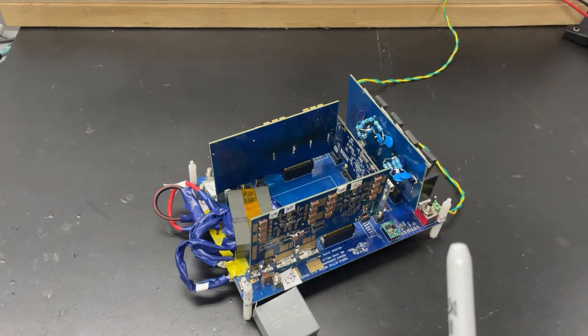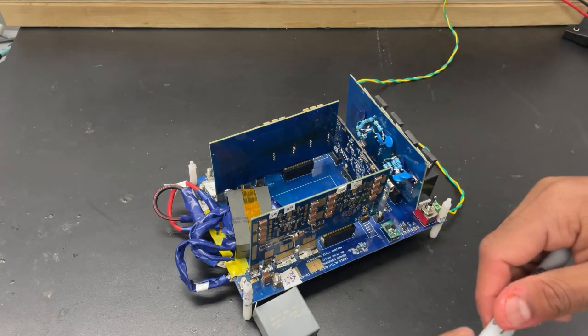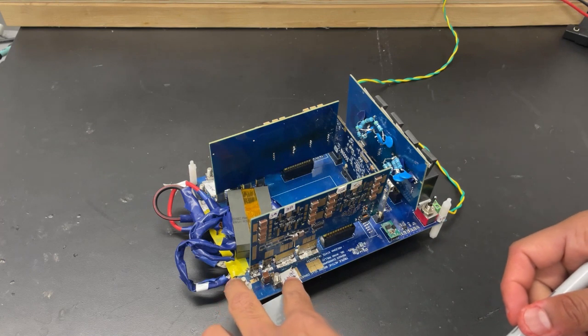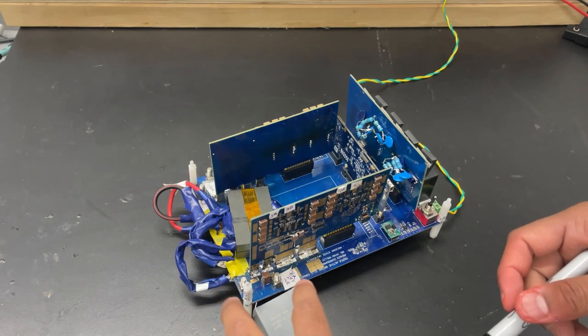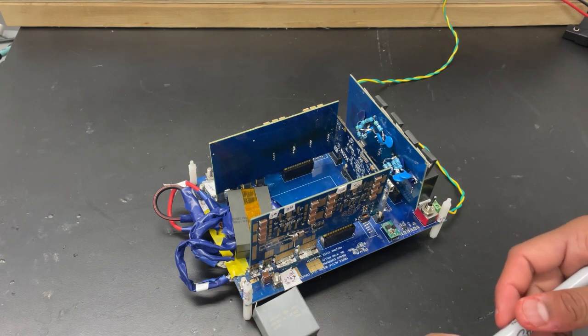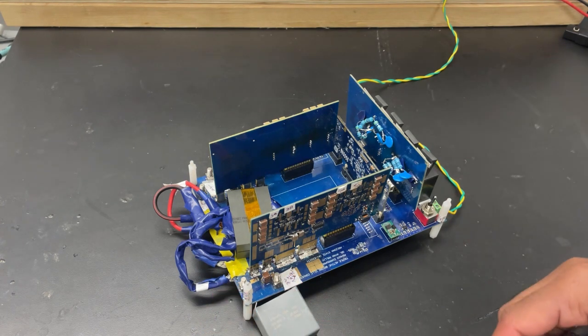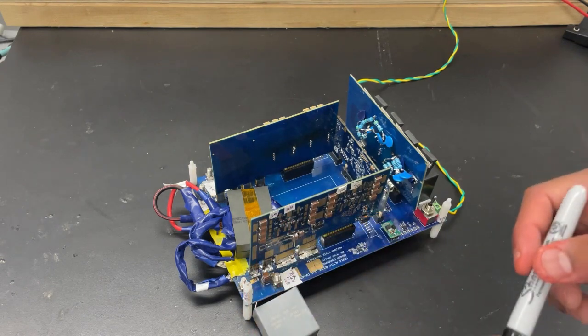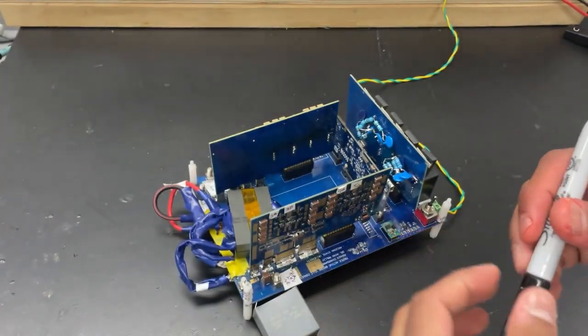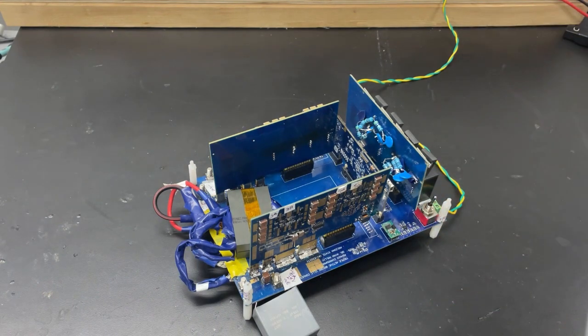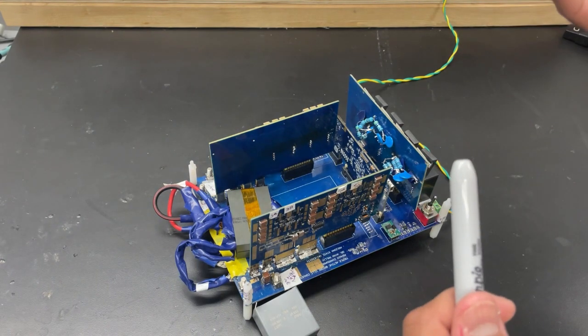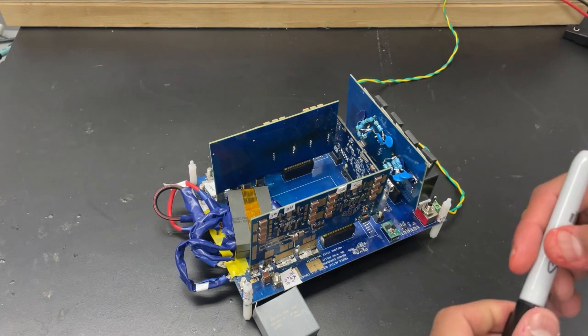So this is a low voltage high current side. The output is obtained at these two terminals, and the nominal voltage is 28 volts, and that is connected to a load that could be something like an LV battery, low voltage battery. We are using 4 devices per switch position on this particular bridge. The reason being, we want to reduce the RDS on. Paralleling the devices reduces the RDS on, and since this is the high current side, we want to increase the efficiency by reducing the RDS on.